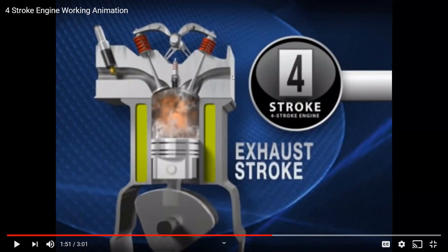Because remember, at the intake stroke, well, let me back up. The exhaust stroke, you're dumping out air that's still really hot and still at high pressure. And then you're exchanging it for air that's back at atmospheric pressure and regular temperature. So in a sense, it's like you've cooled off the air that you did have. What you've really done is just replace it with identical fuel and air that's at the initial conditions, but it doesn't make any difference. So that's why the exhaust stroke and the intake stroke can be combined into a single isochoric process. Because think about it, the exhaust stroke, let me back up like 2 seconds.